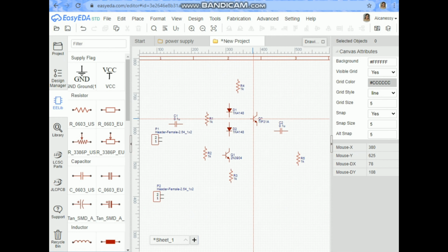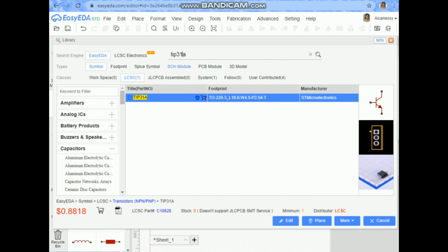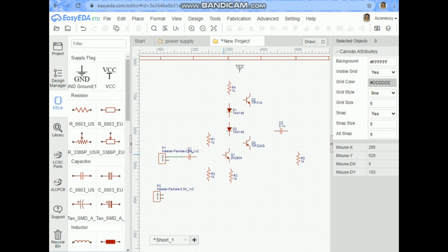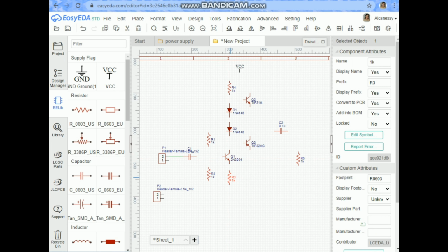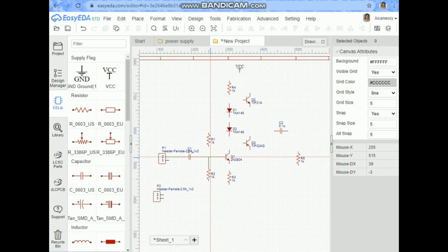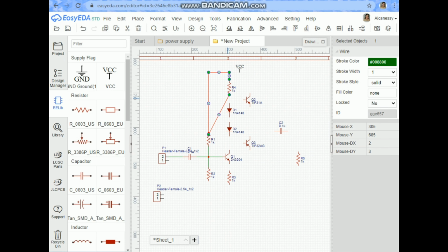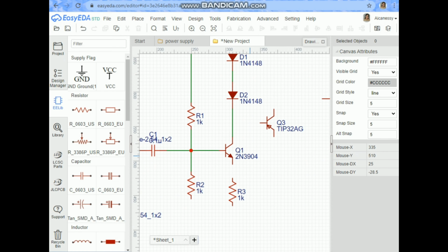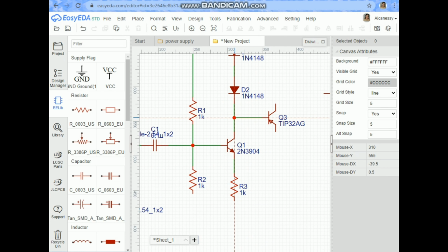Based on the results we got from the simulation earlier, we have seen that the Class AB amplifier configuration is more efficient than a Class A amplifier but is slightly less efficient than a Class B because of the small quiescent current needed to bias the transistors just above cutoff. However, the wrong use of biasing can cause crossover distortion spikes, producing a worse condition.